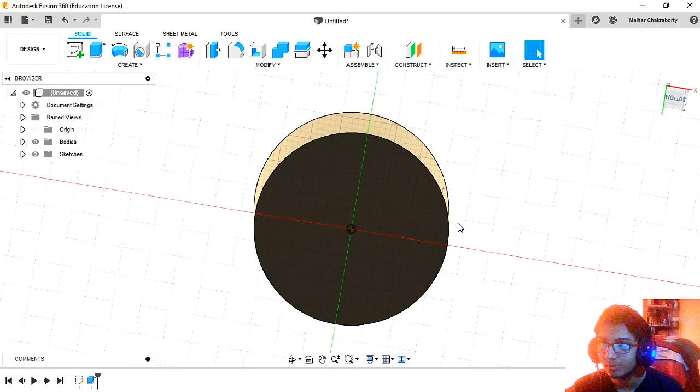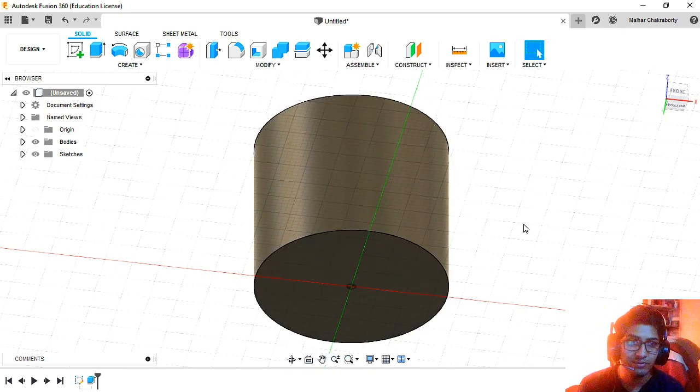don't have a 3D printer yet, but if you are going to print this, you need PLA or ABS filament to print it. And the more material you have, the more the mass, the more filament will be required to print it, and the more the printing time. Maybe this cylinder without infill, I mean, if you don't fill the cylinder properly, but still you need some support materials to actually print it, it will take more than 8-10 hours to print, if not more. And with proper infill, I think this shape will take more than 24 hours to print.